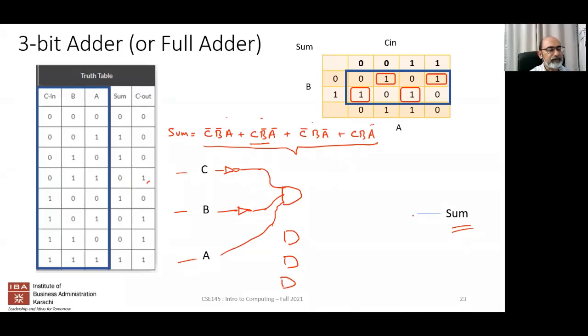And now we want to combine all of these into sum. So what do we need now? So we'll combine all these AND gates using an OR gate. We could have multiple OR gates, or we could just assume that this OR gate takes 4 inputs. Okay. So we could have something like this, which sort of is an overall picture of what the output would look like. So at the end, you're going to have an OR gate. Why? Because basically it's a sum of all of these, and each one of these expressions is simply an AND gate because it's taking a multiplication of several inputs.